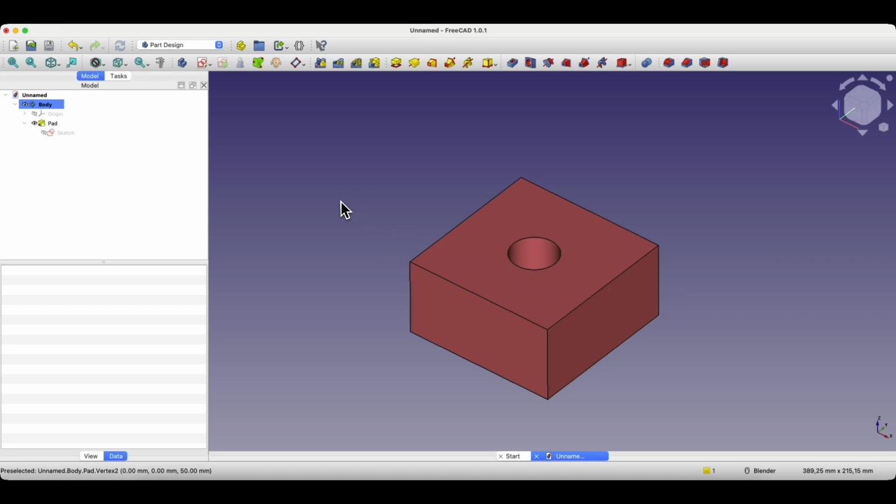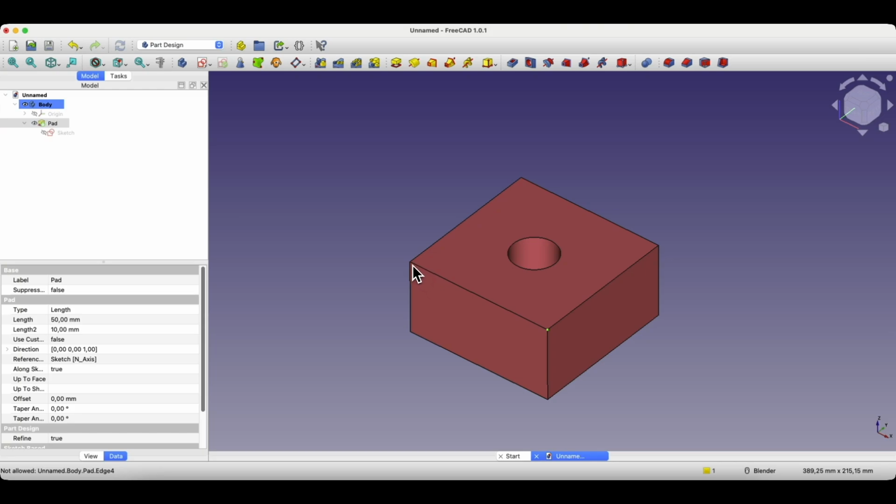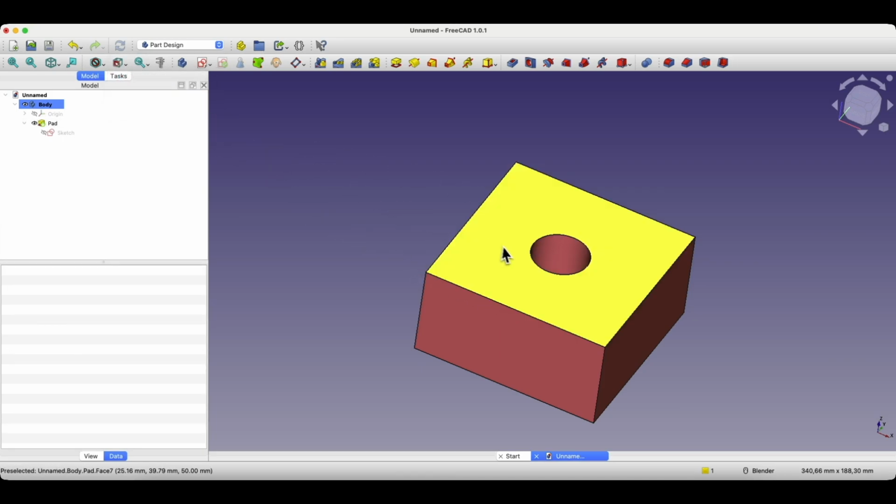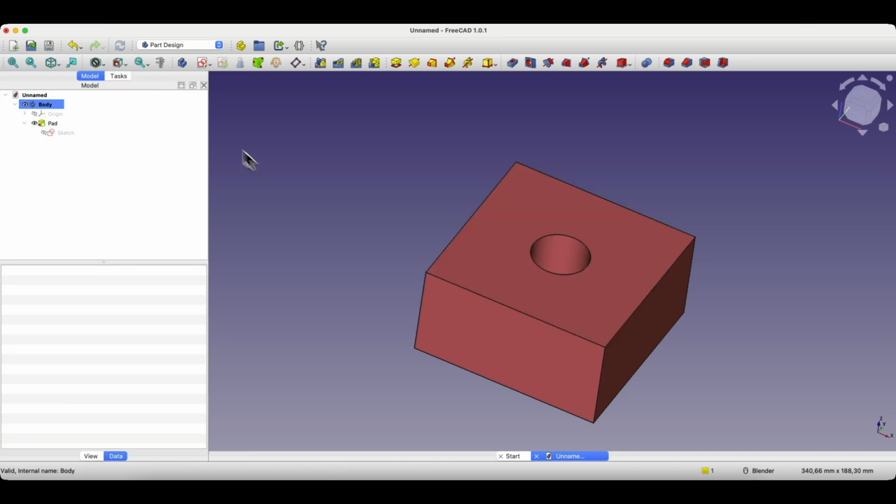And also, when it comes to selecting geometry, we have geometry selection modes here. We can choose vertex selection mode, and then we can only select vertices. If we select edge selection mode, we can only select edges. Next we have face selection mode, then we can select faces, or we choose this option, and then we can select all elements of the object. Selection modes can also be useful in some cases.